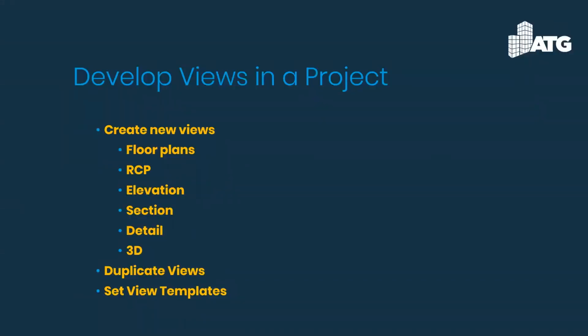All right. So, developing views in a project. When you're starting out within Revit, obviously it's important to understand how to go in and create new views. Within Revit, you have the View tab, and in there you have options to create multiple types of views, brand new views from scratch. You can select floor plans, reflected ceiling plans, elevations, sections, details, and 3D views. Those are all different options that you can go in and create new views for.